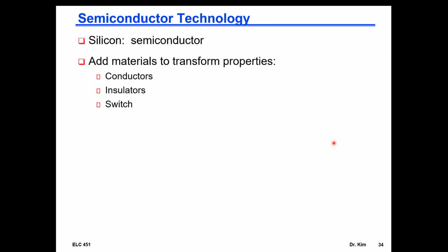So now, just a little bit; you can have a course on semiconductors, but basically, you take a neutral material like silicon that has four electrons on the outer band, and you dope it with some other material that can donate an electron, which makes it n-type, or steals an electron, which makes it p-type. You dope it with ions like boron or phosphorus, something that is close, but not quite on the same column of the periodic table. It's either on the left or the right, and then you can get N or P type semiconductors, and that's where the whole technology comes from.